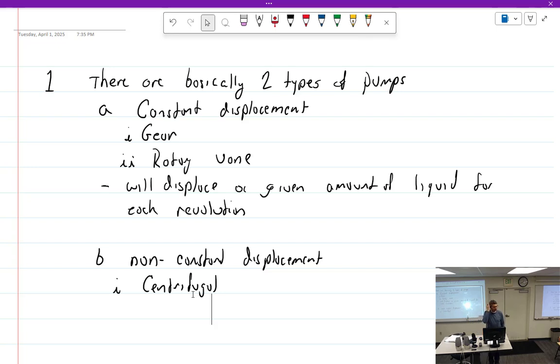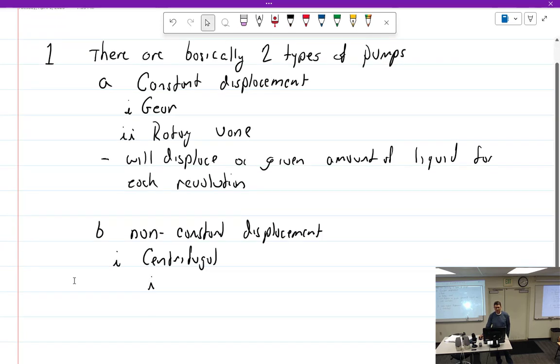So same thing with centrifugal pumps for fuel. If you block off the exit with a centrifugal pump for fuel, what happens? Nothing. You just blocked off the exit. That's it. No problems whatsoever. Where are you going to find these? Well, in most typical situations for any type of aircraft fuel system that uses pumps, you need two. Why do you need two? Safety and redundancy, right? And starting the engine.